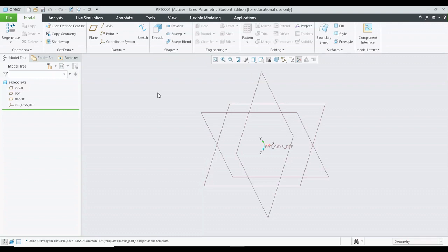If I want to extrude it, extrusion means converting that particular circle into a three-dimensional solid model. Right? So what is happening in extrude is the two-dimensional layout is getting projected perpendicular to the plane on which we have created the two-dimensional sketch. This is quite confusing if you try to follow the definition, but if you see the way we create an extrude, it will be very easy for you. So let us use the extrude option.